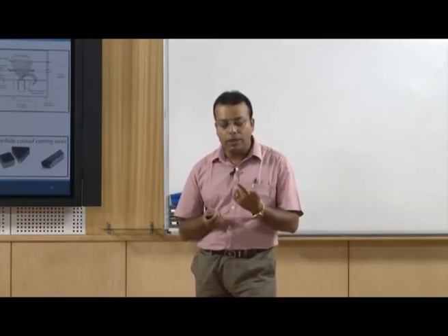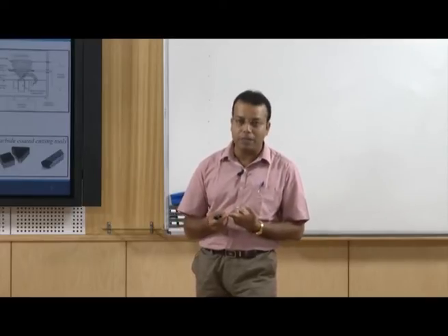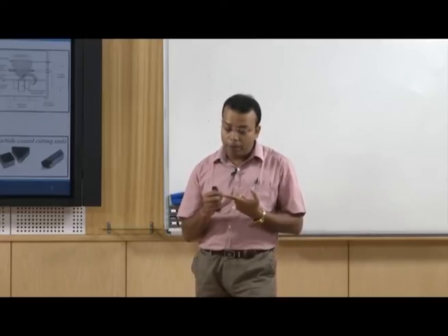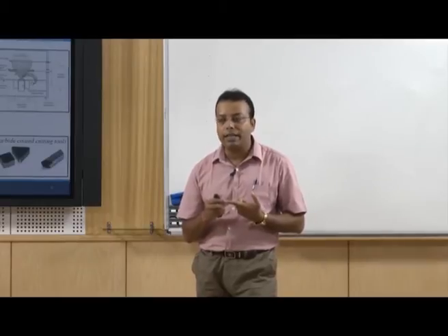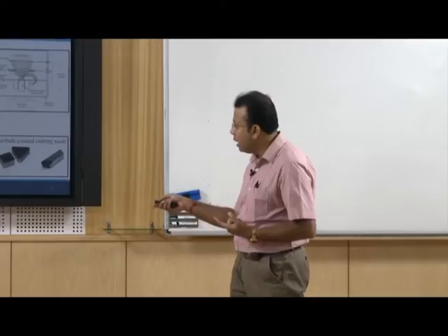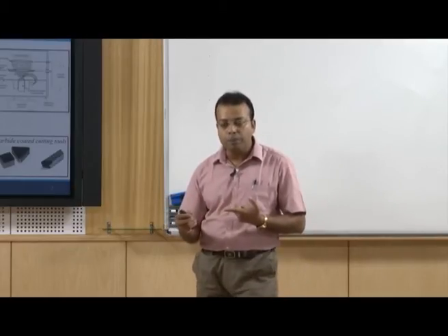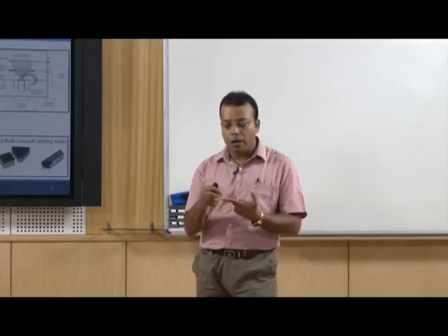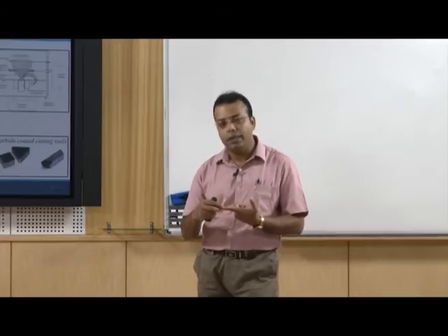So what we do, generally, is use a cutting tool made of HSS, that means high speed steel, and the tip of the tool can be changed easily; we generally call it an insert. So that material is made of titanium carbide or titanium nitride. So when it is worn out, there is no need to change the whole tool; you only open the screws, take out that insert, and put a new insert over there.